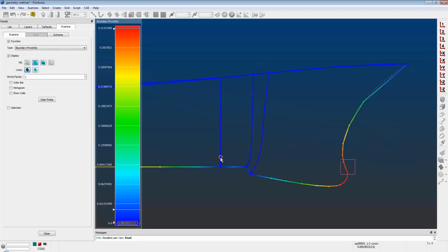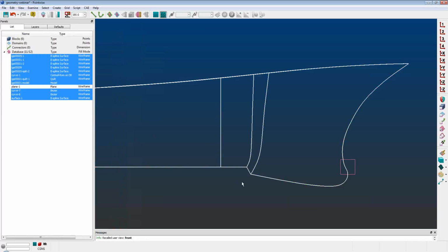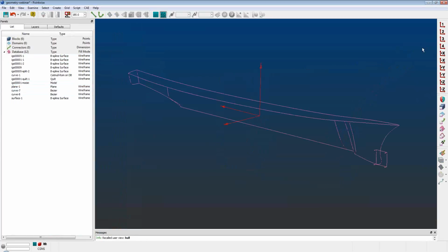By moving the cursor over the shared boundary regions, you can determine the gap between the surfaces. In this case, Travis has picked one of the points between the newly modified surface patches to highlight there is actually a gap between these surfaces. It helps to note this gap value. In this case, it's about 0.0002, as we're going to use it for some of the upcoming steps. So there are two general ways to deal with these gaps. I'm going to use some simple schematics to describe both approaches.